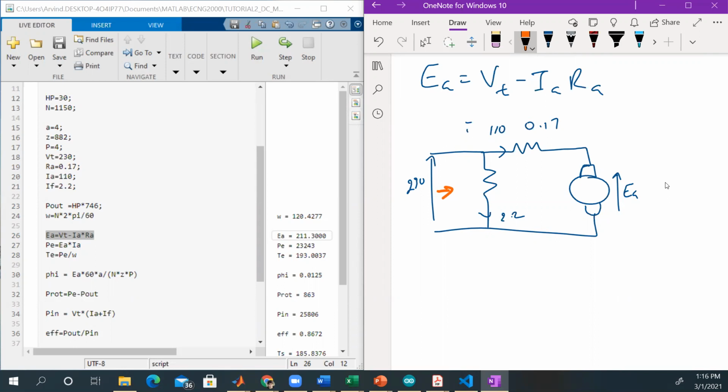Those are the things that represent the rotational losses. We have the electromagnetic power here, PEM. At the output, at the user side, we have P out. The losses that take place here are the friction and windage, or the rotational losses. You hear them referred to as both.